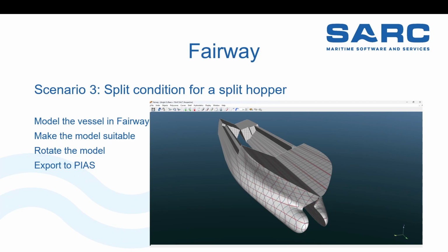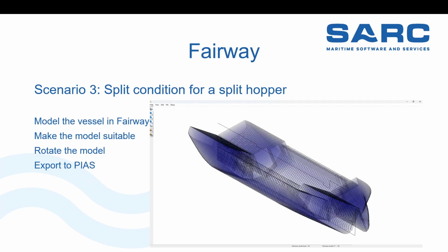And actually, we need to do these calculations. It's a bit rubbish because for stability, it's an empty catamaran if you make it like this, and it will always comply. But for longitudinal strength, I believe that at Bureau Veritas, they do some calculations to study the strength of the hinges for this. So that's why we need to go through the motions of a complete stability calculation for that. Okay. This is what we sent back, and I'm not sure if it's visible here.